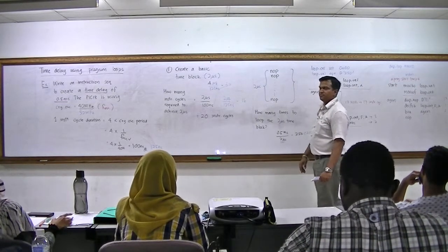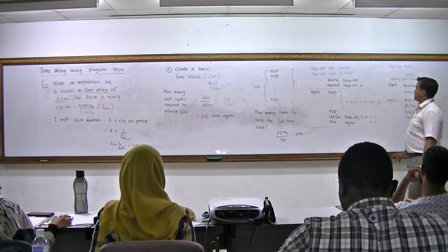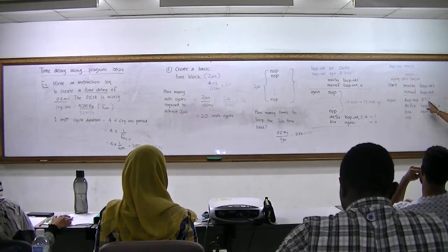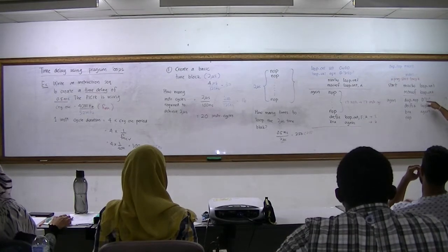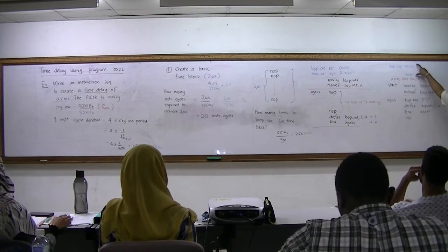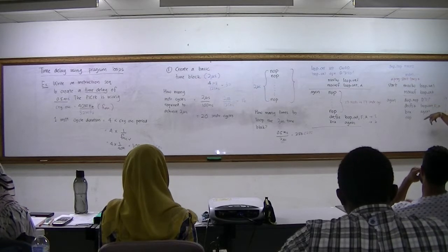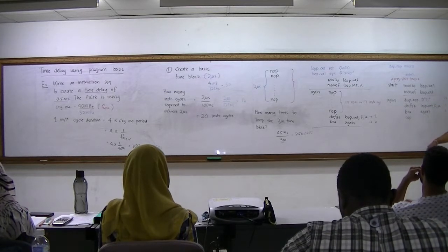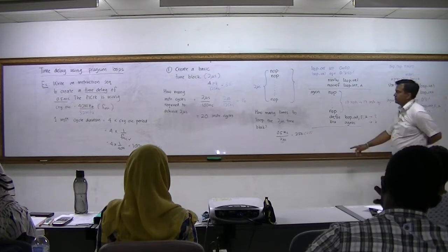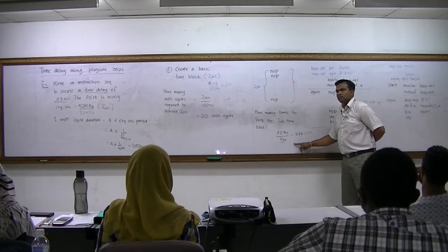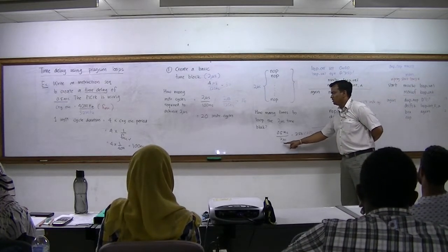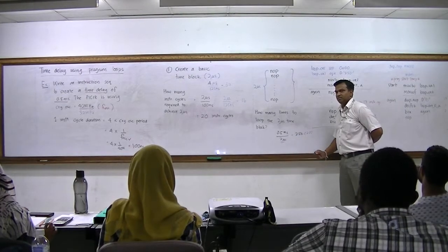It's minus 3. So you'll get 29 here. So you need to pass 29 here. So just change this value to 29. So this macro is the same. So you just put 29 plus 1 plus 2. Okay? 32 instruction cycles. Does this change? No. Still, you need to loop this basic time block 250 times.